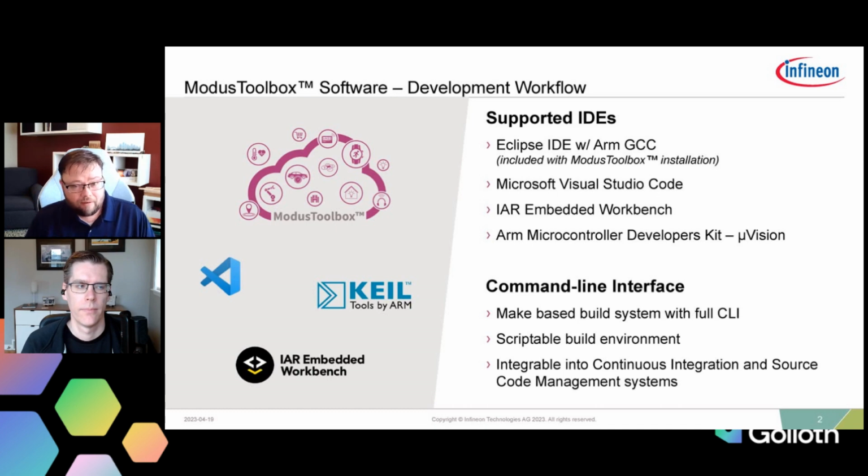But at the heart of Modus Toolbox is a make-based build system. And so this gives you complete access to a command line interface. You can do everything from being able to create a very scriptable build environment with pre-build commands, post-build commands, integrated into continuous integration systems, be able to tie it into your own source code management system, whether you're using GitHub itself or GitLab or SVN, right? All these things tying together at a very low level to give you complete control, complete flexibility to really allow you to create a development environment that works best for you.